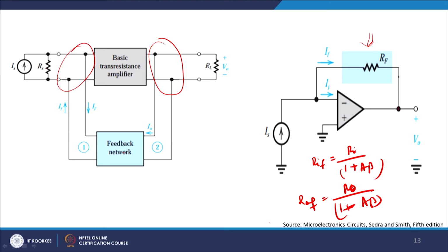So, when you have these types of amplifiers sitting in between your load and your source, then you can change your output impedance in such a manner that it becomes almost equal to the input impedance of the external load, and therefore, the maximum power will be transferred from the chip or the circuit to the external load, right. So, that is one of the major advantages of having feedback, that you can control the impedances at the input and output by simply choosing the type of configuration which you want, and that is the important part which you will see here.